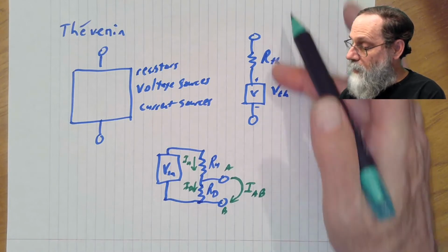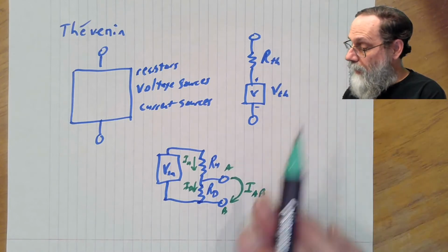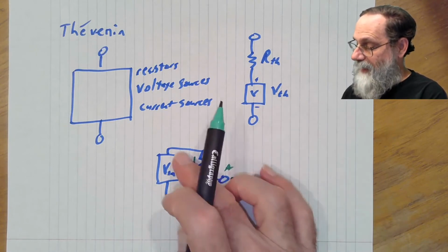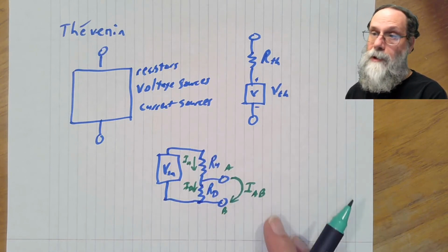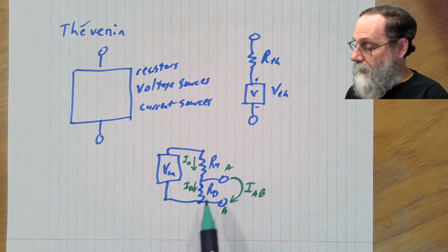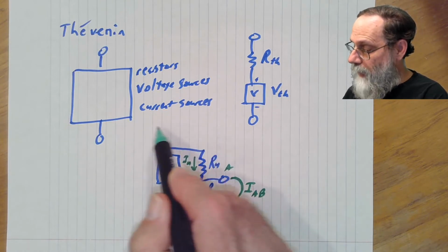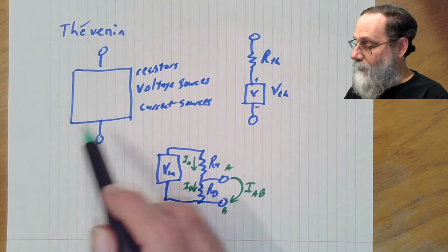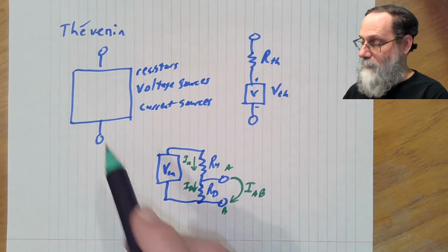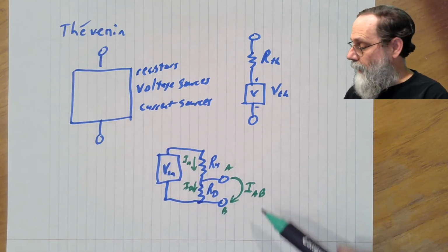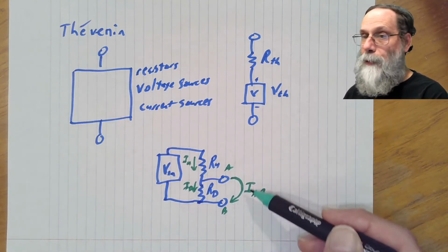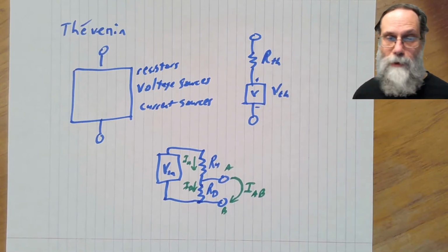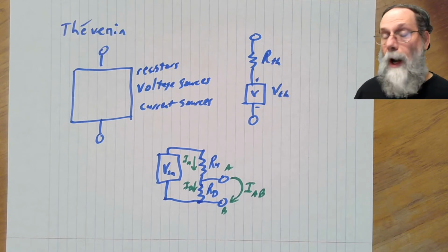Because we can determine how this thing behaves if we can find an equivalent circuit to this one that gets the same behavior for voltage and current at these two output ports. Because the whole idea of the Thevenin equivalence is we can't see what's going on inside the box. This is a closed box. We can't see what's in it. All we can do is put voltage across it, measure current. And so if we can get the same voltage current behavior from this circuit as from this one, we've gotten the equivalence. All right, so how are we going to do that?